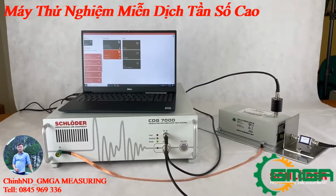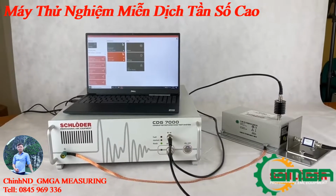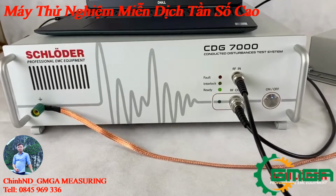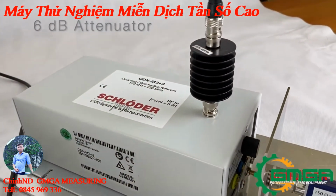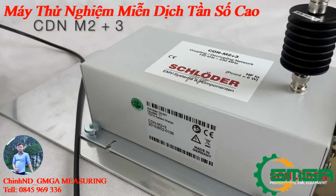by the IEC 61000-4-6. The test system consists of the CDG 7000, which goes directly to the 6 dB attenuator, which is required by the standard. The attenuator is connected to the CDN M2 in this case.